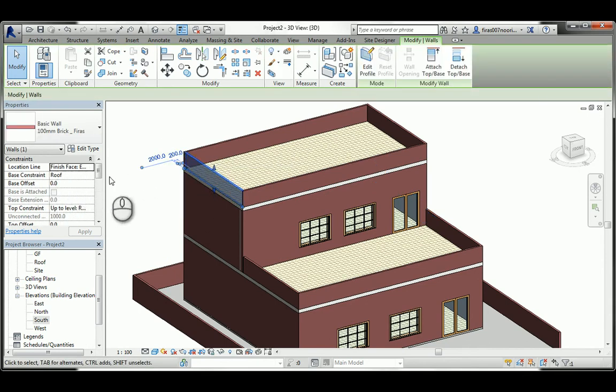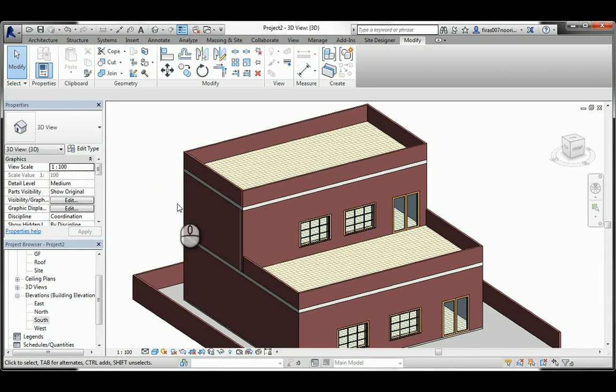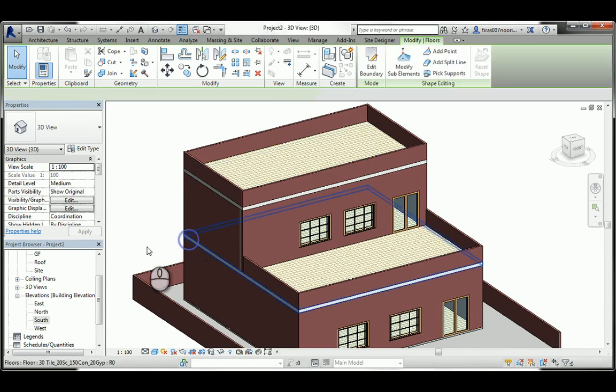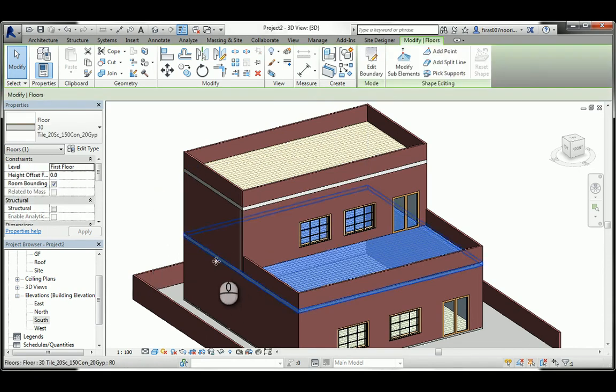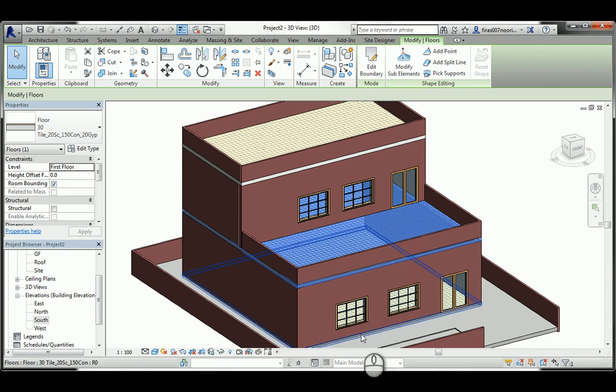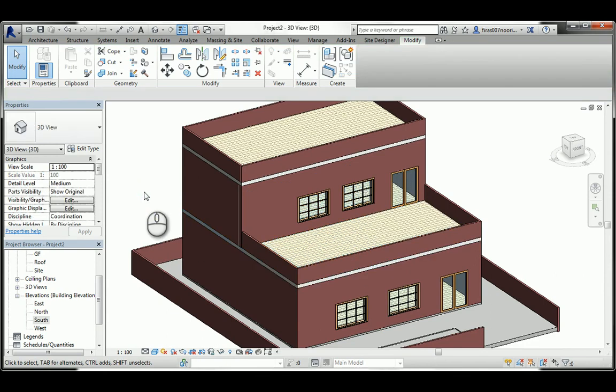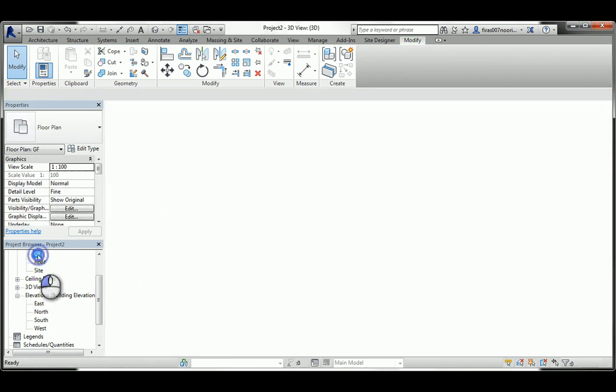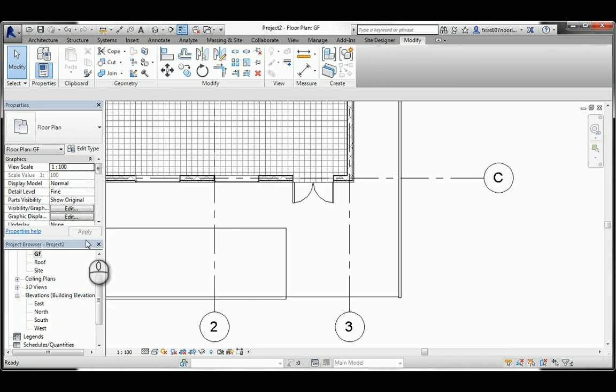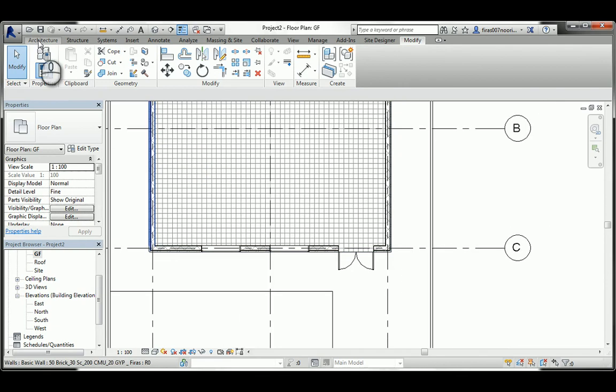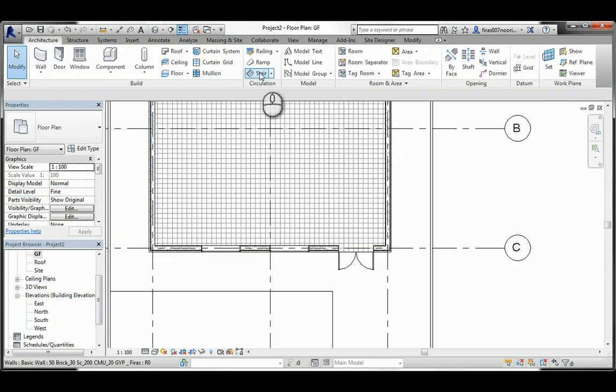So now we just need to create our stairs, so it should be here anyway, between this level and the ground here. So I need to open a space for it first, or actually let's design the stair first and then we see. So I'm gonna go to the ground floor, and in the ground floor I'm gonna go to architecture and then go to stairs, this one.